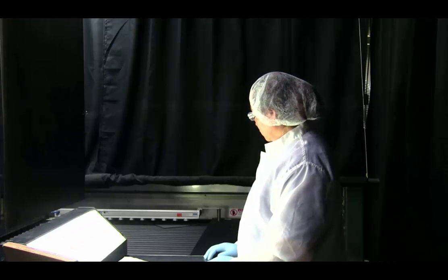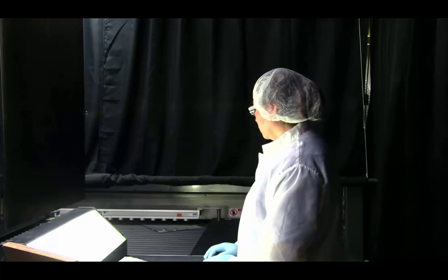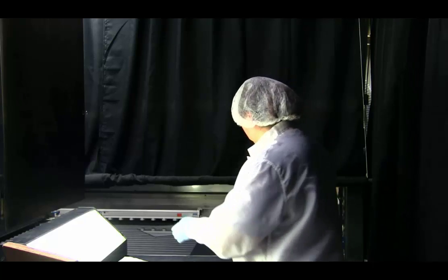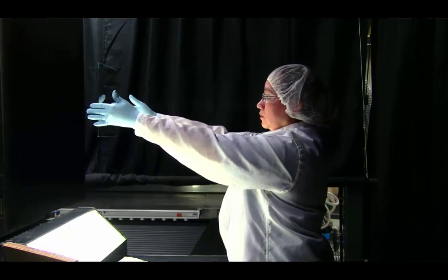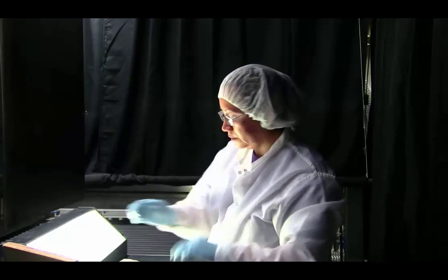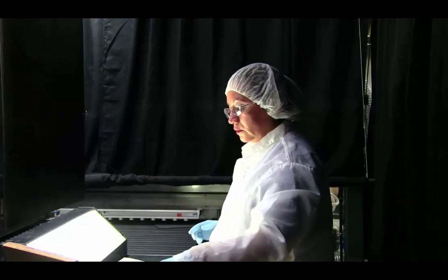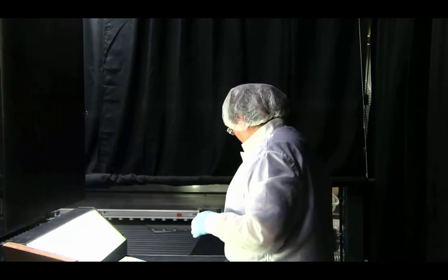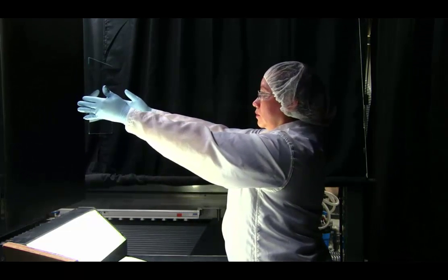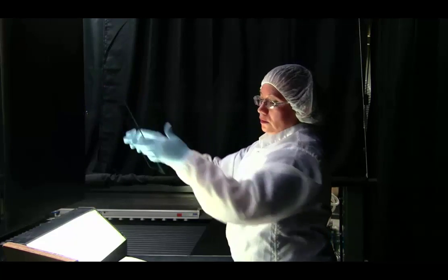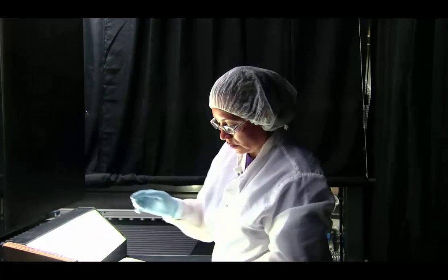Q3 inspection is performed in line on the production floor as demonstrated by the inspector in this video. Parts are conveyed out to the inspector, picked up and held perpendicular to the eye. Barrier gloves are used to protect the glass from any contamination. The use of the fluorescent backlight and overhead light, not visible in this video, provide the proper lighting environment to identify digs and scratches per the Q3 criteria.